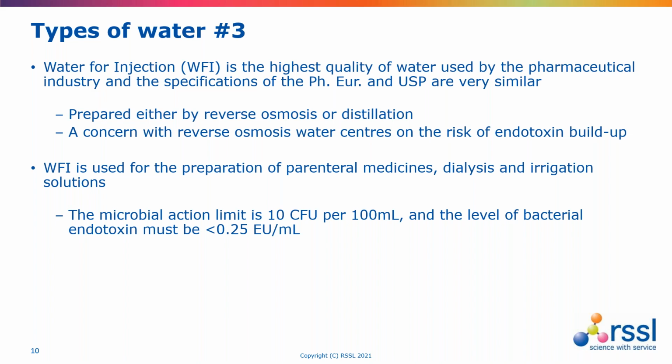So WFI is used for the preparation of injectable medicines, for dialysis, irrigation solutions, turning into steam for autoclaves and so on. And the Pharmacopoeia requirements are no more than 10 colony forming units per 100 ml. So by specifying per 100 ml, that makes the membrane filtration method mandatory.